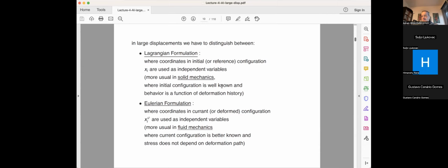On the other hand, if you take the simplest case of a fluid, like a Newtonian fluid, basically the only stress that is of interest to you is the true stress, which is in the deformed configuration of the fluid. And then the simplest behavior is to assume that the true stress is proportional, with the viscosity coefficient, to the symmetric part of the velocity gradient. And here you describe your constitutive behavior for the true stress.